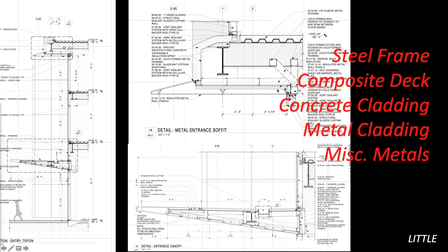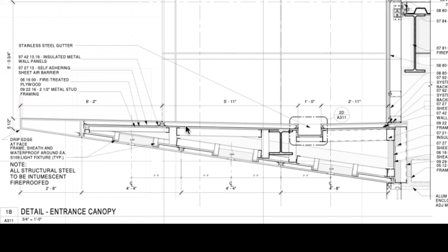And the steel channels, let's see if we can get a good label on this one. There's a mineral wool insulation under here. There are some attachment brackets, and then there are these panels that are suspended from these attachment brackets. So we have all of these nice devices that are also helping to support some of these metal panels. We have a little gutter that's worked in, right? That's a terrific detail. And look at all this miscellaneous metal.